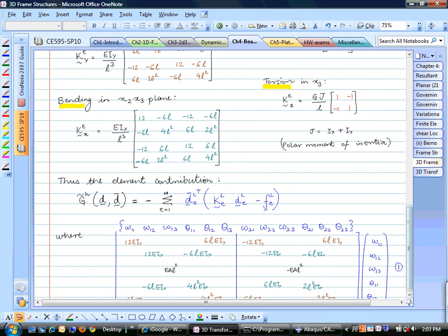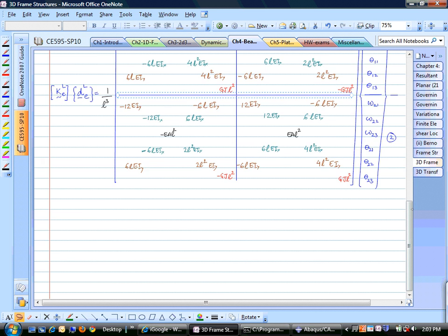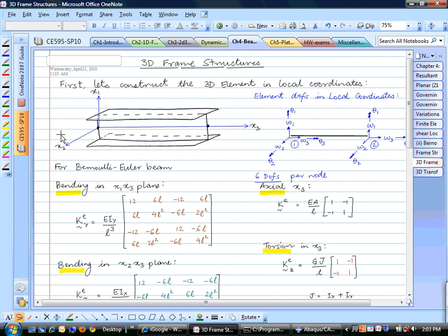So, for example, in this case, the three-dimensional frame case, you have, let's say, this I-beam which is oriented along x3 direction. Its major principal axis is about x1, and the weak axis or minor principal axis is along x2. If the displacements and rotations are small, you can decouple both of them and treat them independently. But as soon as you get into large displacements, large rotations, all this theory breaks down, and there is a much more advanced theory of geometrically exact beams that you would have to resort to.